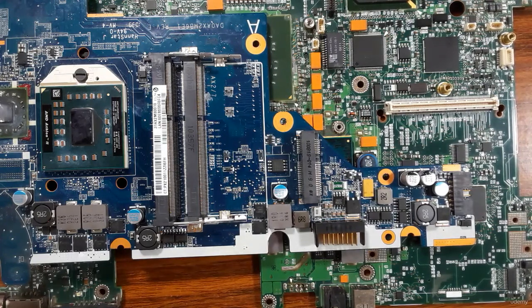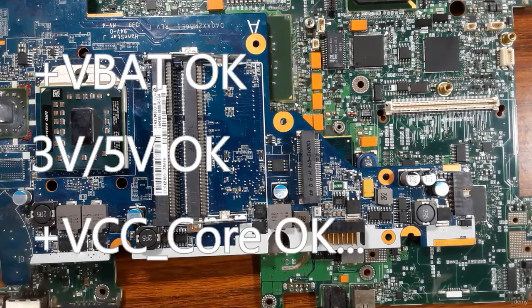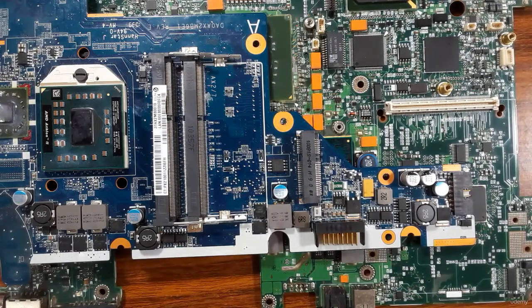You find the 19 volt, you find the 3 volt and 5 volt. Computer is on, all voltages are present. The 5 volt for the USB connector, the 3 volt are present in the pin number 8 of the BIOS. You find all voltages, but the computer still not on the screen, still black screen or white screen.